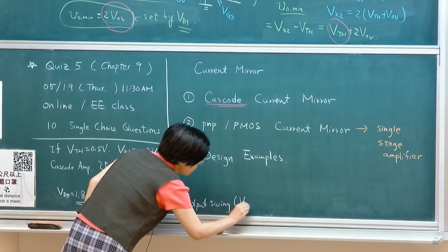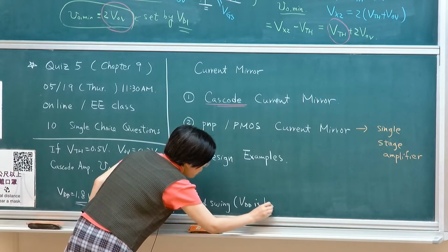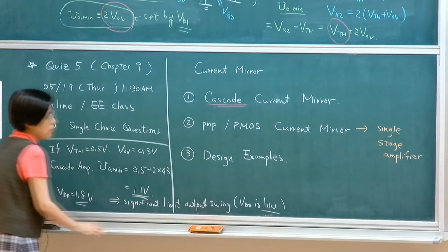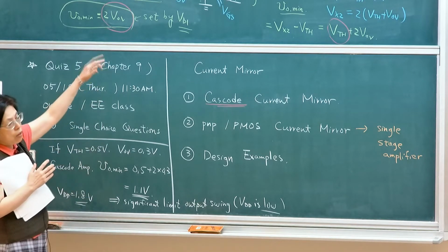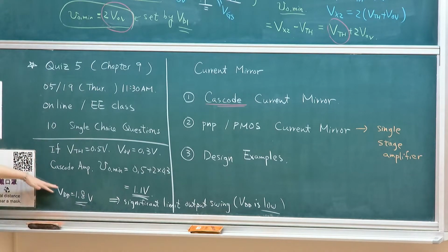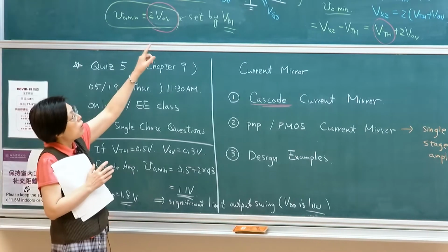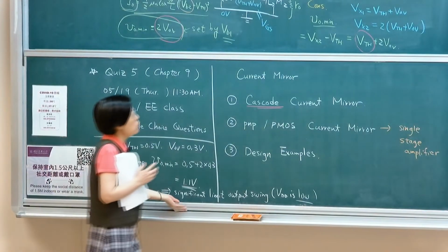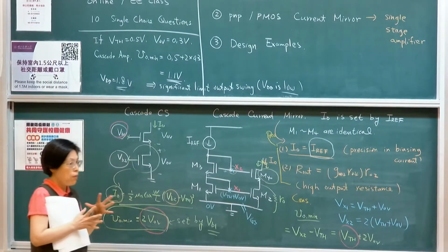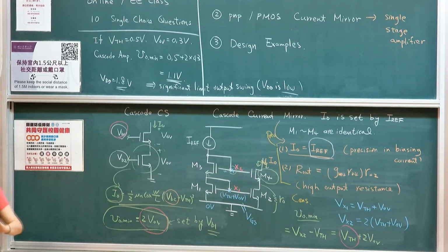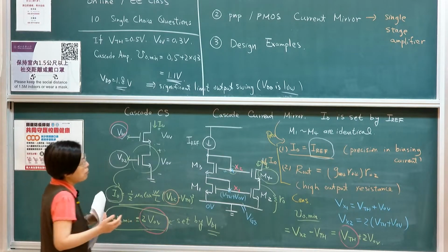When VDD is low, so when your supply voltage is, as we already discussed, below 2.5 volt, you basically have very little margin, especially when you do cascode structures. It will be even worse because of this limitation on your bias voltage on Vx2. So this will be one threshold worse, and one threshold is 0.5 volt. That's significant margin in a lot of analog circuit design, especially under low supply voltage circuits.